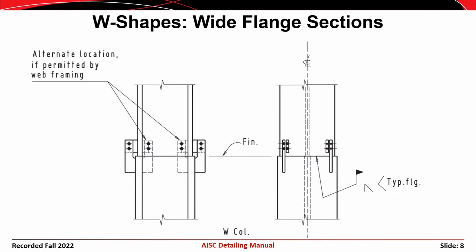That's important because when you stack these members on top of each other, like you would in a column tree, like we have shown here, the inside faces or the inside surfaces of the flanges all line up. So there's a common plane here, and there's a common plane over here, and that makes the detailing or the connection design much easier when you use members that have common T dimensions. So that's why W flanges are well suited for building members.